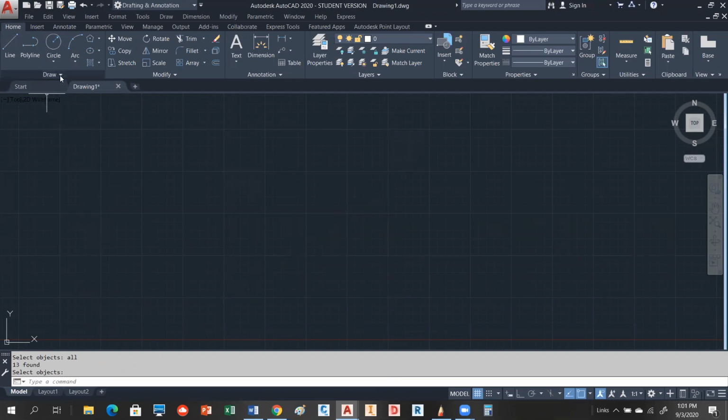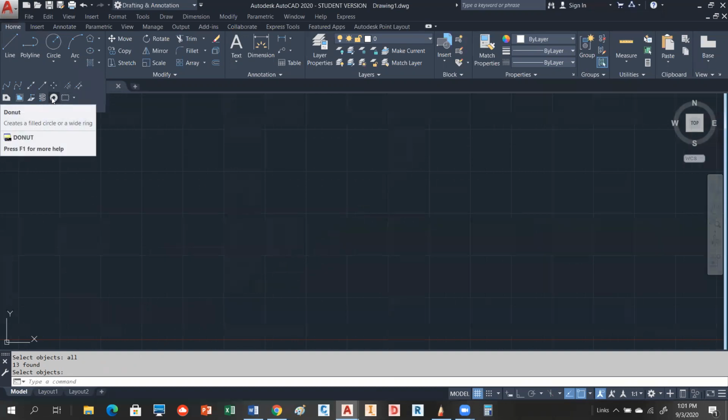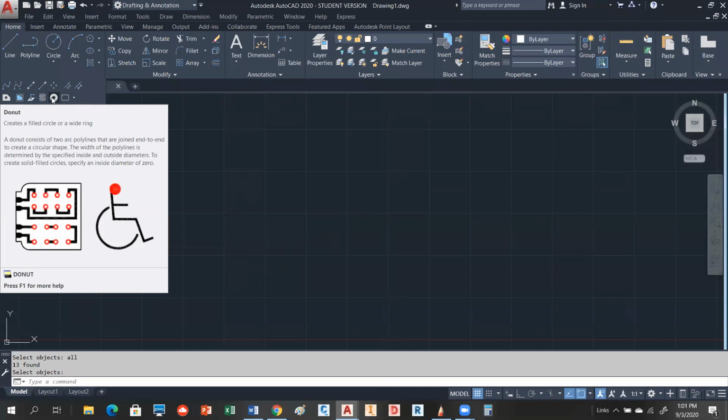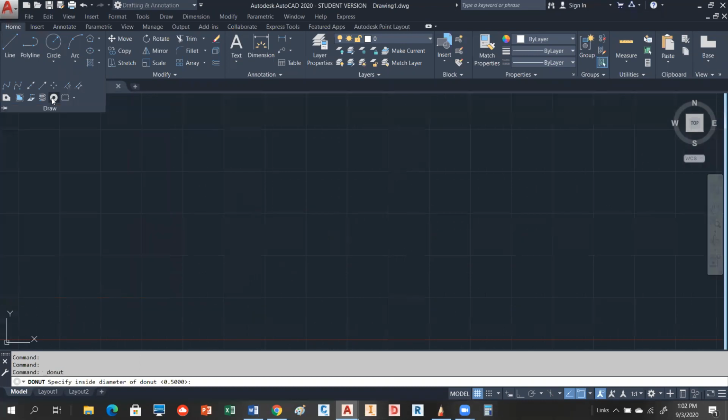The donut is also located down here, right there. They do spell it D-O-N-U-T, so that's not a misspelling, that's how they spell it. And D-O, I believe, is the alias if you're typing it. So we would just select that, and notice it's going to ask you to specify an inside diameter. There is a default value in there, so if you want to accept the 0.5, you can. Go ahead and hit enter.